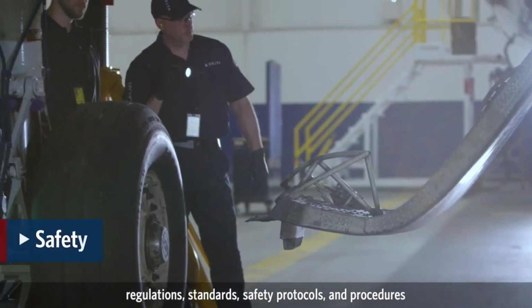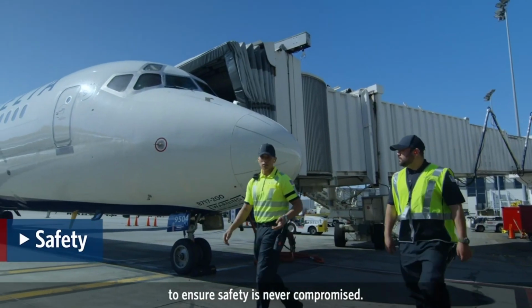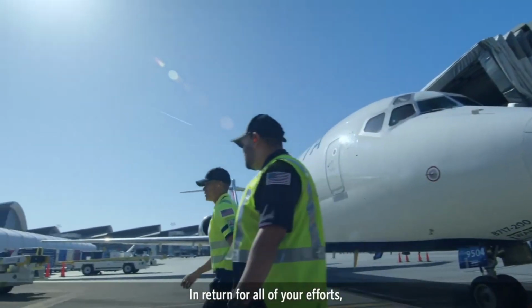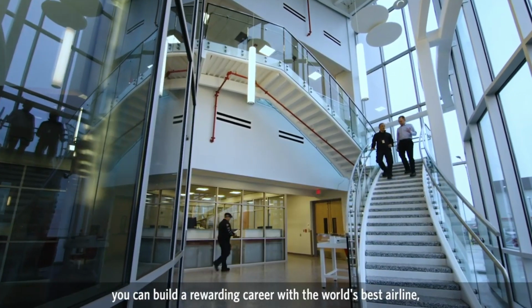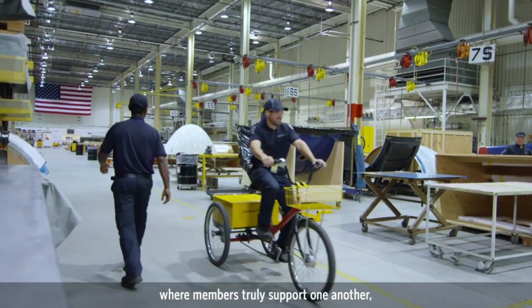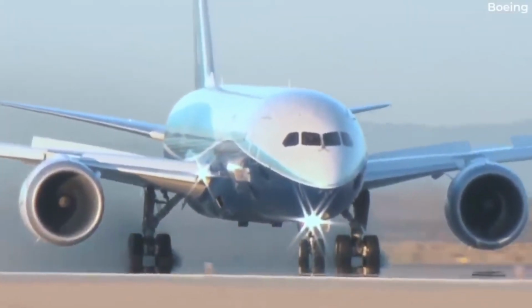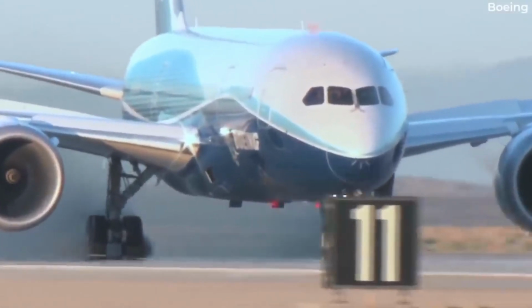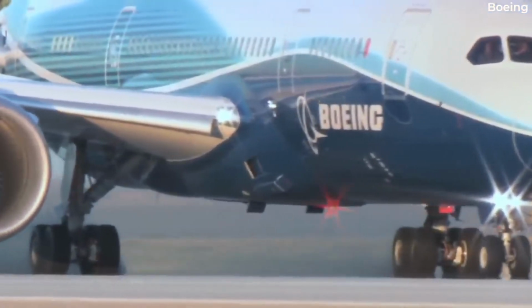14 CFR Part 125, Certification and Operations: airplanes having a seating capacity of 20 or more passengers or a maximum payload capacity of 6,000 pounds or more, and rules governing persons on board such aircraft. This regulation applies to private and non-common carriage when such operations are conducted in airplanes having 20 or more seats, excluding crew members, or having a payload capacity of 6,000 pounds or more.